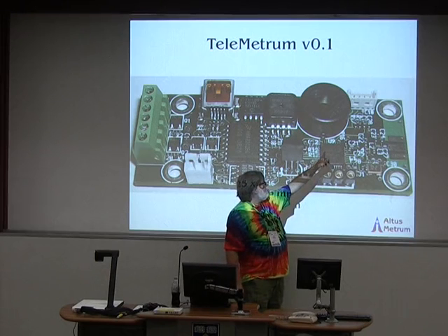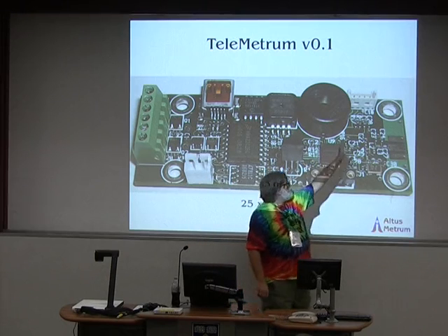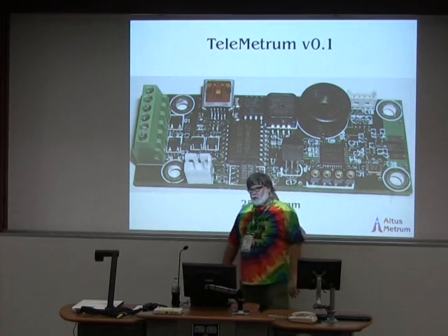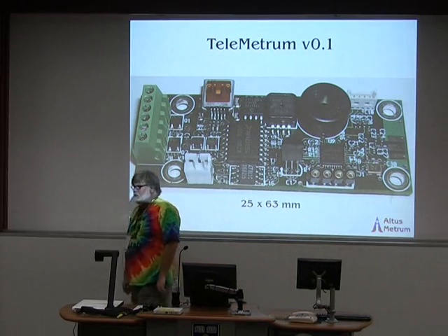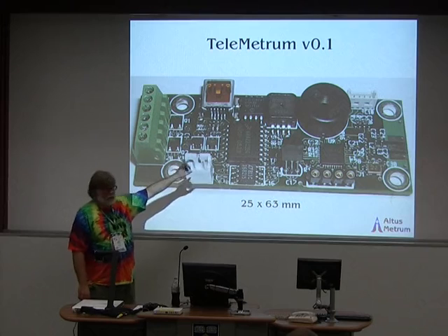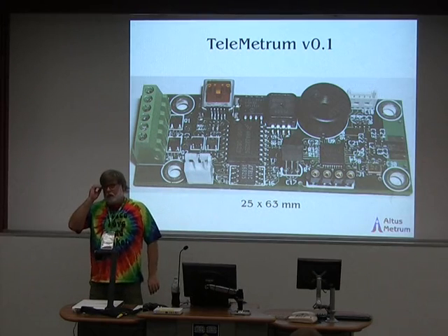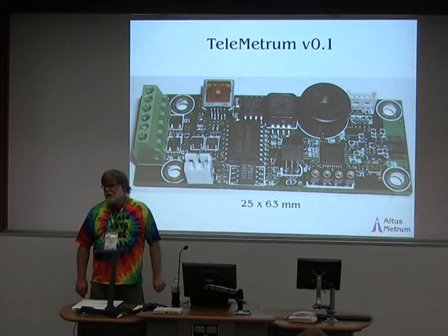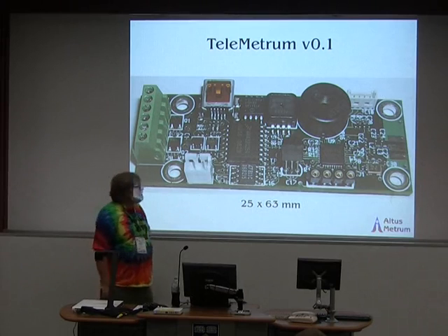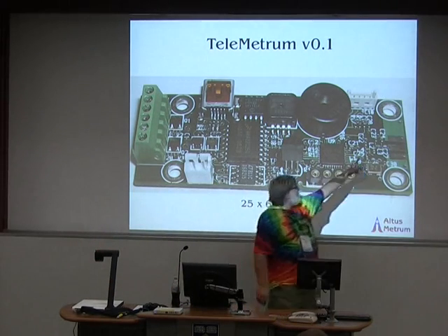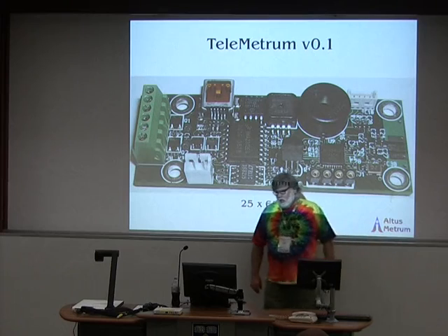But just to point it out, this is the interesting part. That's the CC1111 right there. And this part over here is the UHF balun and filter assembly to basically take the differential output and input interface on that transceiver chip and bring it out to a single-ended antenna connection at 50 ohms over here.